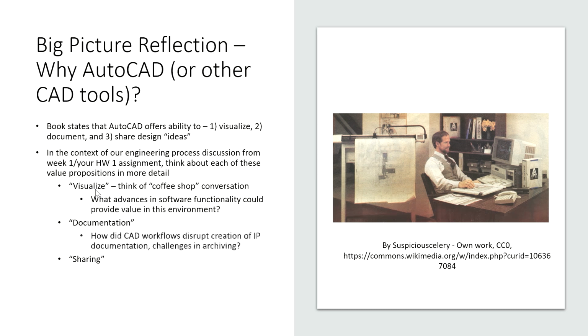So yeah, a drawing is always a living document because you can revise the version, you can always update it, but it should always tell whoever opens the drawing or prints the drawing who made it and the date, because then you can think, oh well, if it's 2022, then there was such and such product. Now in 2023 we have two versions after that. Okay, so always put the right documentation on each drawing.